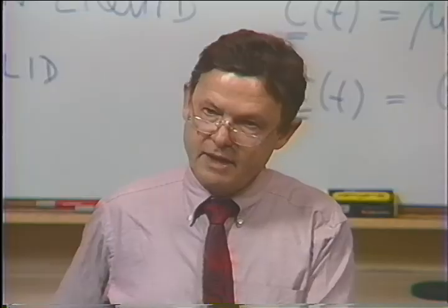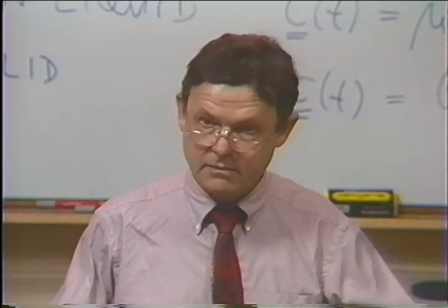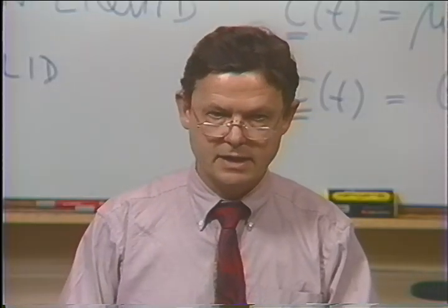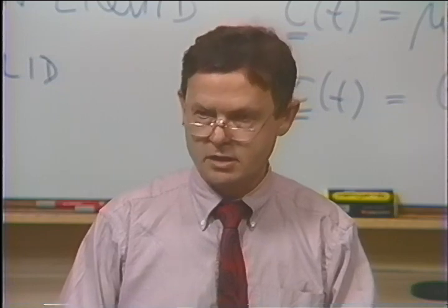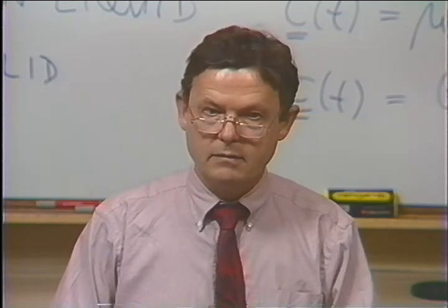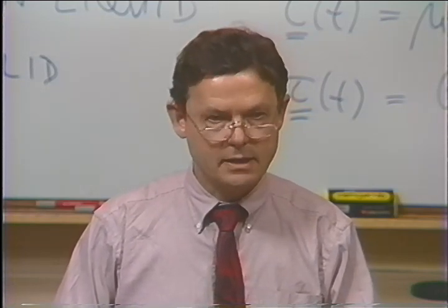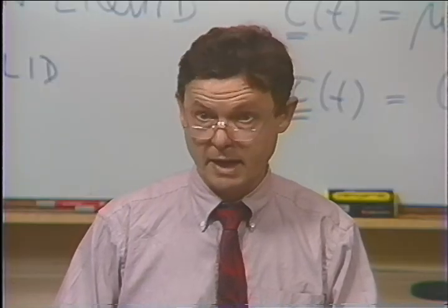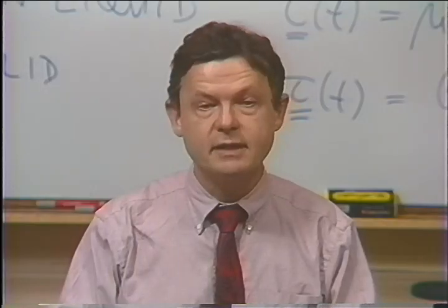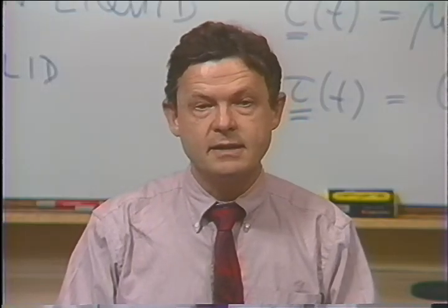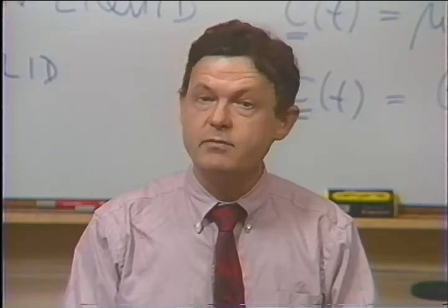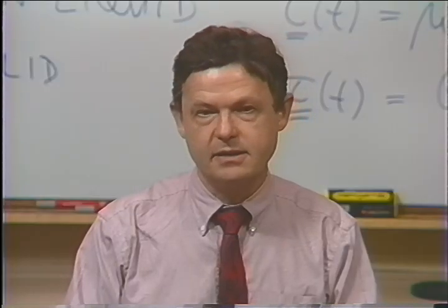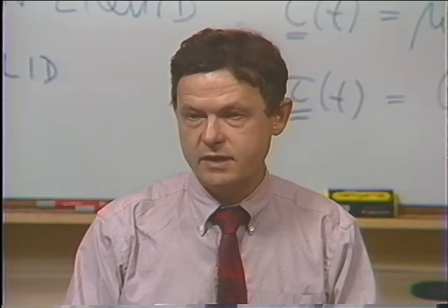So with that, we have a complete definition of the linear viscoelastic behavior from a phenomenological point of view. We will do a few exercises, some calculations, predict some material functions with that equation, and compare to experimental evidence. And then we will talk about possibilities of measuring the relaxation modulus, measuring G of t and H of lambda.